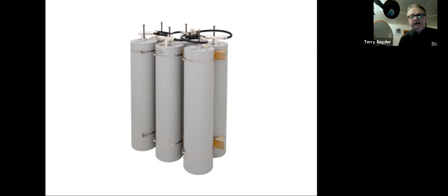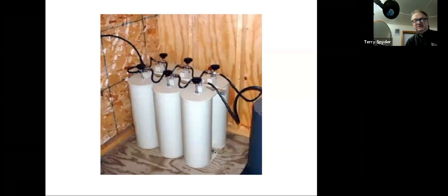That's how you keep that receiver from ever seeing the transmitted signal. It's all done through these cans and the magic that's in there. And also those cables are specific lengths to facilitate the proper tuning of them. And if somebody says to you, hey, I got a scope, I bet we can tune that duplexer, don't let them touch your duplexer. If you own a repeater, don't let them do it, because it's very delicate to do.